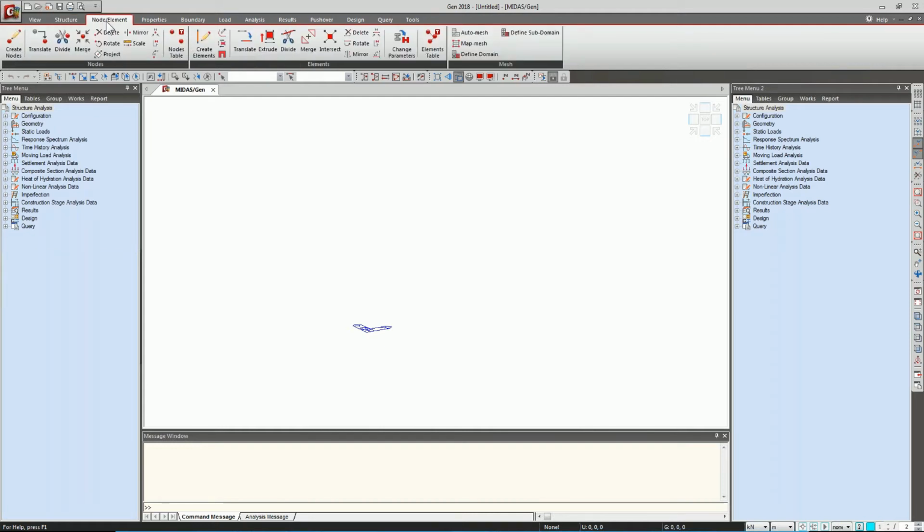Lastly, we have CAD-based modeling tools, where we can start from scratch creating nodes and elements. In this webinar session, we will be using these CAD type of functions. So we'll be starting with creating the nodes first. While creating the nodes, I'll copy them 4 times at a 6 meter distance, and the coordinates are 0, 0, so I'll just click on apply.